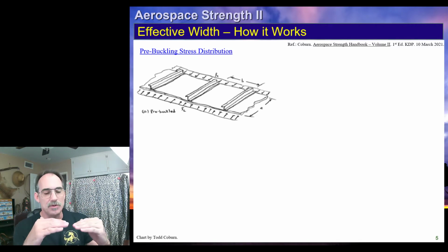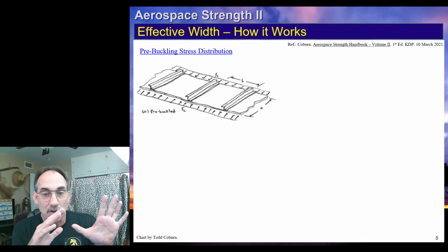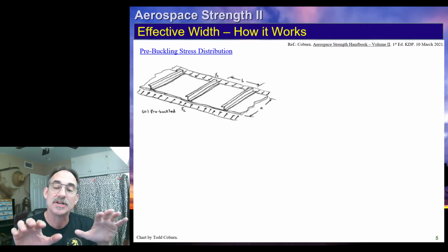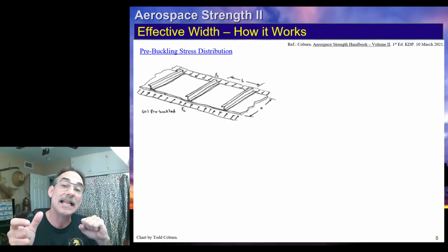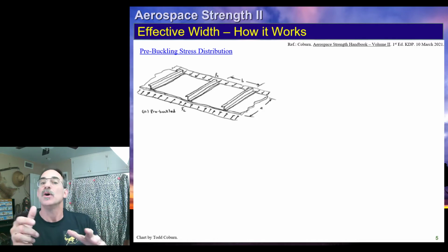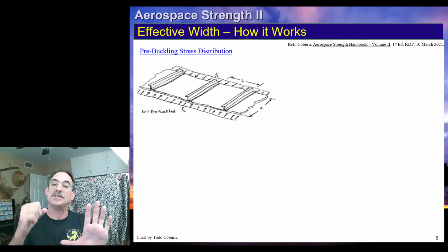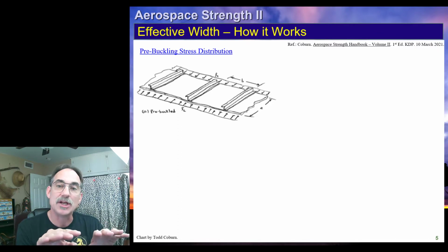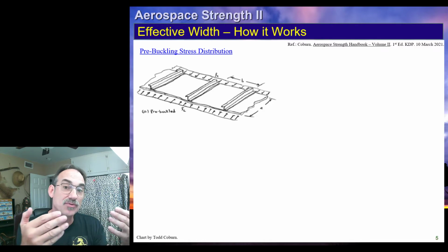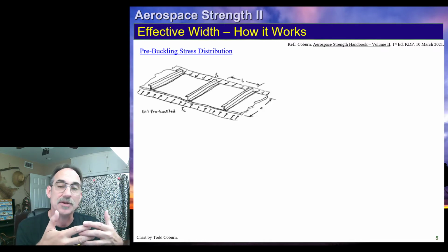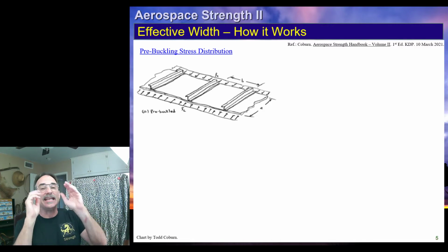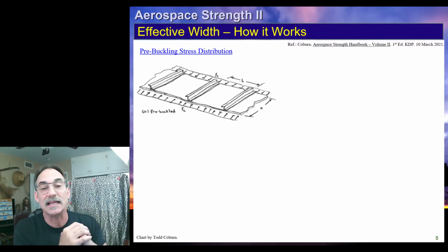If we focus on the stringers, for example, and we have a thin skin with longitudinal stringers, the stringers have some stiffness and are primarily axial load-carrying members, which, because they're distributed at different positions, carry the bending in the fuselage. And as we have low loads, we get increasing stresses on the skin and stringer that are distributed at the same stress value. But as our stress climbs, the skin begins to get softer as it approaches its buckling allowable.